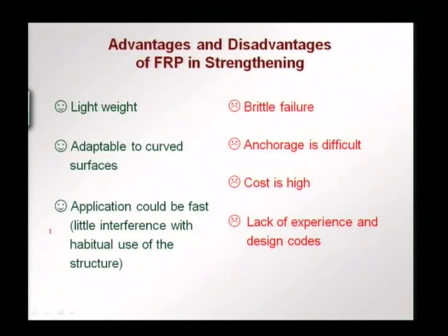However, we also have some disadvantages or difficulties. One of it is that we have brittle failure. We saw in the case of the tensile test that we have linear behavior and then we had sudden failure. So, there could be a brittle failure. So, we have to ensure that the failure stress of the FRP is never reached in an application, otherwise you will have a sudden brittle failure.